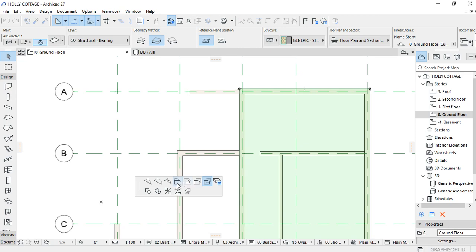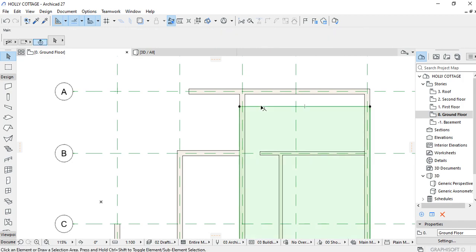Okay. So again, left clicking here gives you other options, such as offsetting that single edge. So you could offset the edge. You could offset it from here, say up to set distance 1000 millimeters. So again, we could be able to offset only one edge.